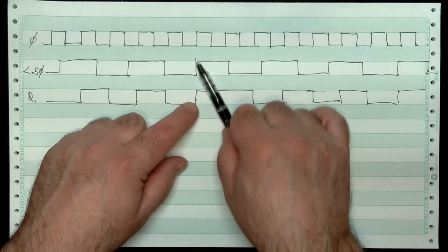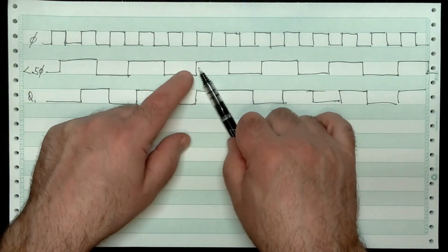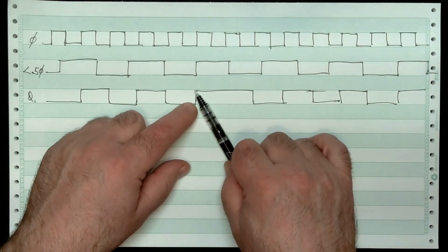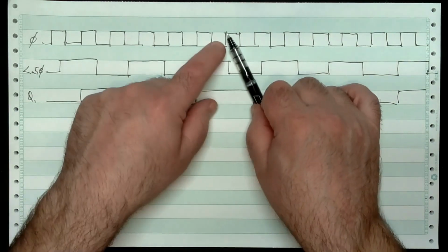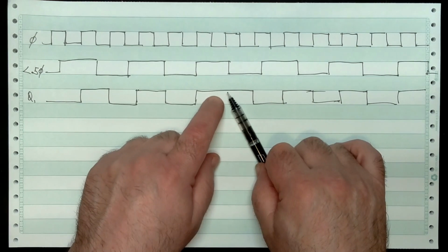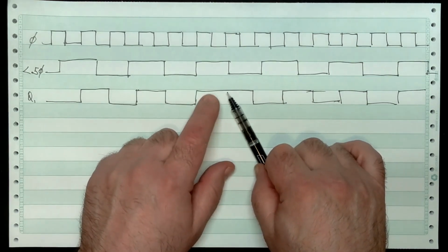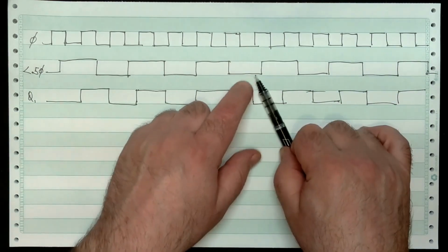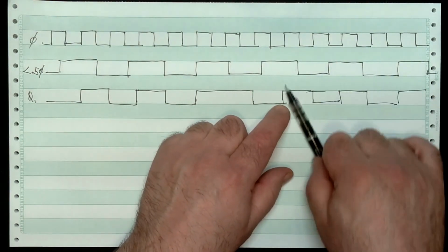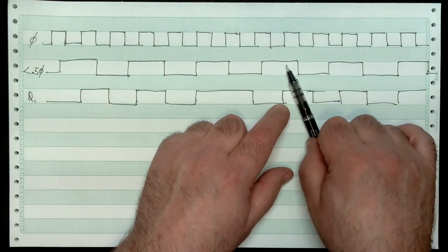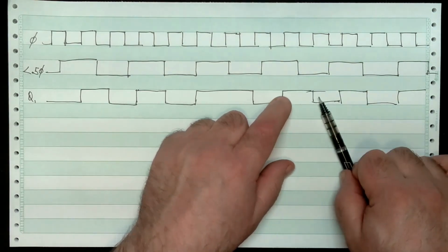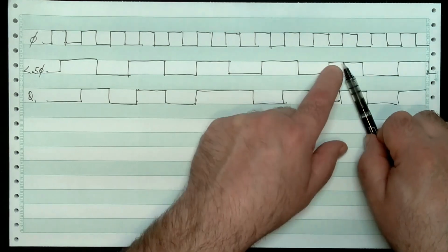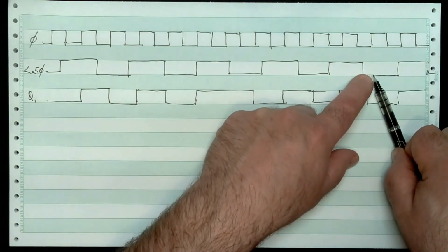Rising edge. It sees maybe a high. Maybe this is just a little bit before that one. So, okay, great. It's high. All right. Rising edge here. It's high. It stays high. All right. And this is what we're going to see is the jitter we're going to see in a minute. The next rising edge here is low, so it goes back low. Rising edge here is high, on a high level here, so it goes high. Rising edge, it's low, it goes back down. Rising edge high, we go high. Rising edge on a low, it's low, and so on.